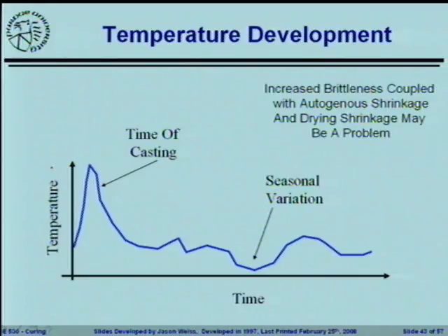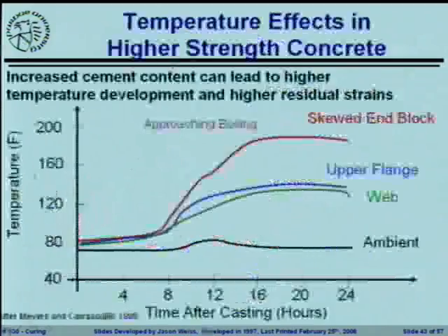It was very warm. I will point out that this particular concrete that we're looking at is concrete that's cast on a 70-degree day. So in Austin, you would say that's pretty mild temperature for them to be looking at. There's the heat spike that we see. This is obviously the heat of hydration. Temperature drops back down, and then we see some wiggling that accounts for seasonal variation and daily variation. But this is a pretty typical temperature development curve.